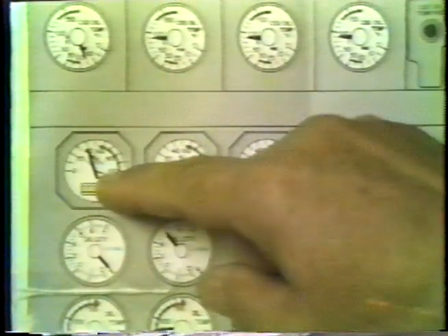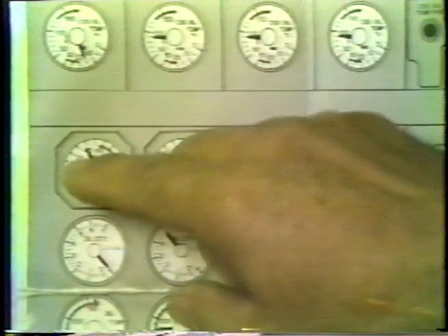In addition, the gauge has a max pointer which lies over the red radial, and if for some reason the engine should overspeed, the pointer will move the max pointer to the maximum value at which the RPM has been reached. And this removes any discussion about how high the RPM went. Any one of these four gauges can be reset by a master reset on the center instrument panel, which also at the same time resets the EGT gauges and the N1 gauges.